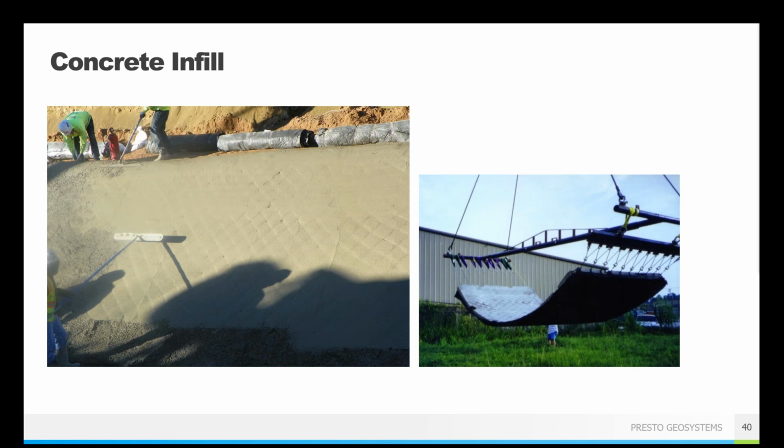But yeah, you're typically going to have that 3-inch deep concrete and you are screeding it to the top of the cells. You're not overfilling it. You don't want to have additional concrete on top of the cells because those cell walls create those mechanical breaks. It would break up through any of the overfill and it would just become loose, broken concrete that would slough away on its own. So that's why we do say screed to the top of your cell wall. So however deep your cell is, 3, 4, 6 inches is how deep your concrete's going to be.